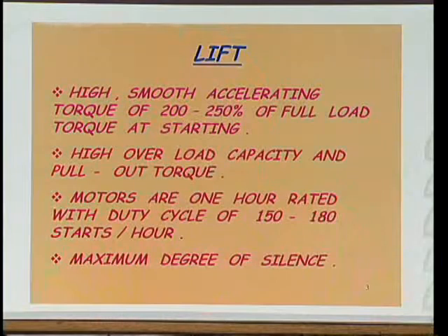We can define the duty factor. It is the ratio of the on time of the motor divided by the on time plus off time. It is called the duty ratio. Here for the lift, the duty cycle will be 150 to 180 starts per hour.